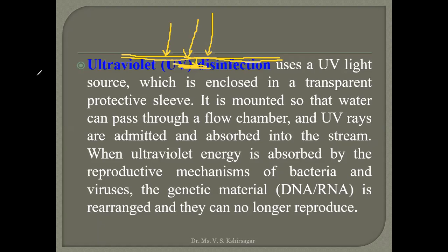Then the greater the water age, for example, we can take the example of Pandharpur city. Water treatment plant is established in the Manisha Nagar. Water reaching the Manisha Nagar people, that water age will be maximum 7 minutes, 8 minutes. Okay. Water reaching the people who are staying near the Vitthal temple, that water age may be 35 minutes, 40 minutes.